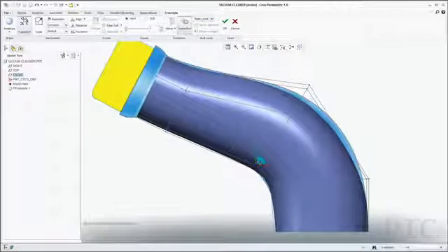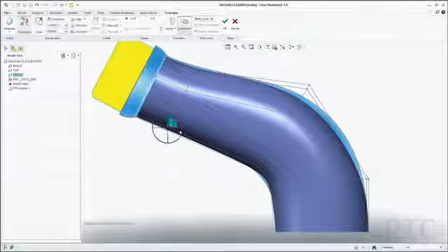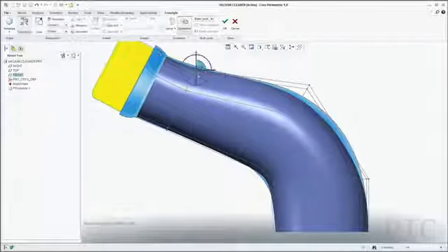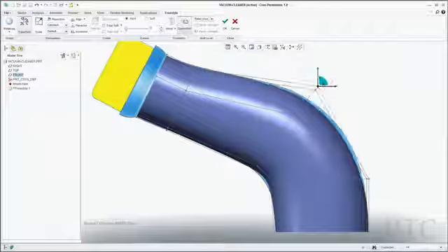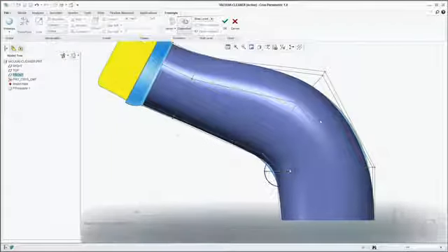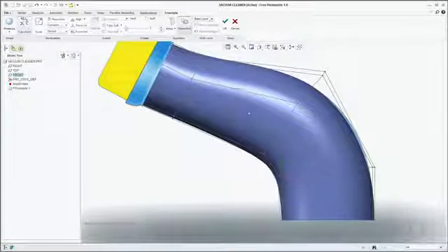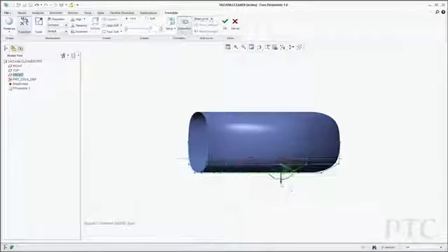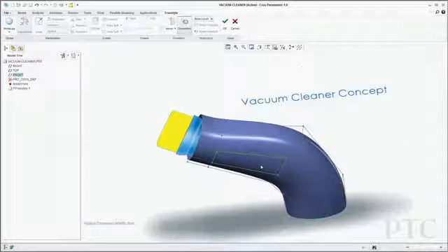So to do that, I can simply select the front face of the control mesh, and I want to connect it to the corresponding back face of my mirrored geometry. So to do that, I'm going to select the face and use Mirror Connect. That will punch a hole going through my product.